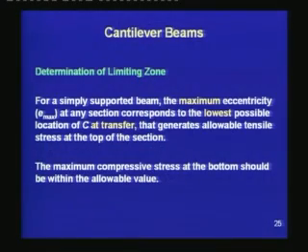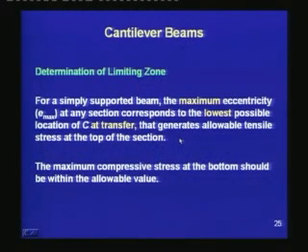For a simply supported beam, the maximum eccentricity, which will be referred to as Emax, at any section corresponds to the lowest possible location of C at transfer. This generates allowable tensile stress at the top of the section. Thus, the maximum eccentricity Emax is determined corresponding to the lowest position of C at transfer. The maximum compressive stress at the bottom should also be within the allowable value.